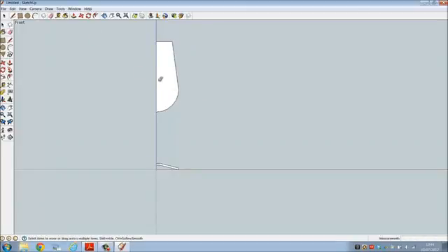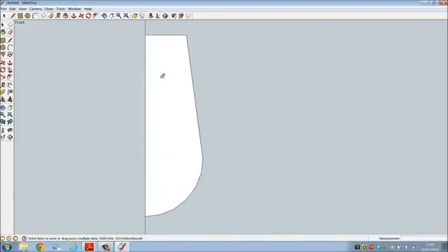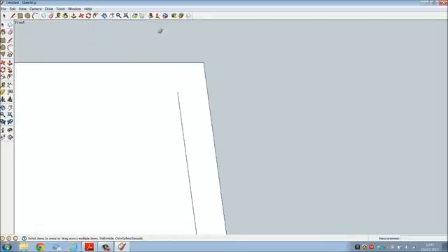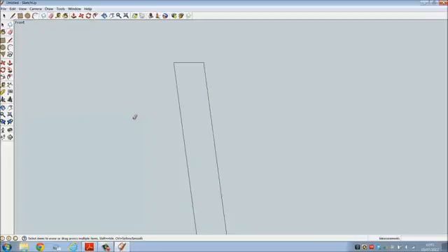And now we're going to assign the glass material thickness. So to do so, we select the command offset, select the profile, move the cursor in to the glass, assign it a value of 3 millimeters, and erase the lines that you no longer require as shown. Now it's a simple matter of joining the dots or extending the line. So draw a line from the endpoint parallel to the edge as shown. Erase the line to the left hand side.